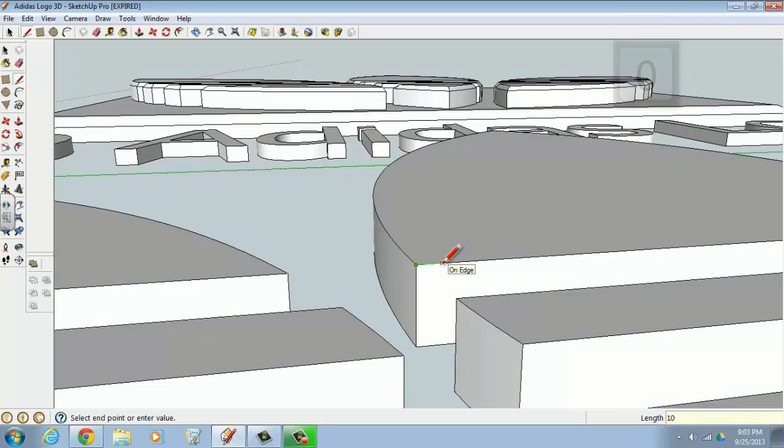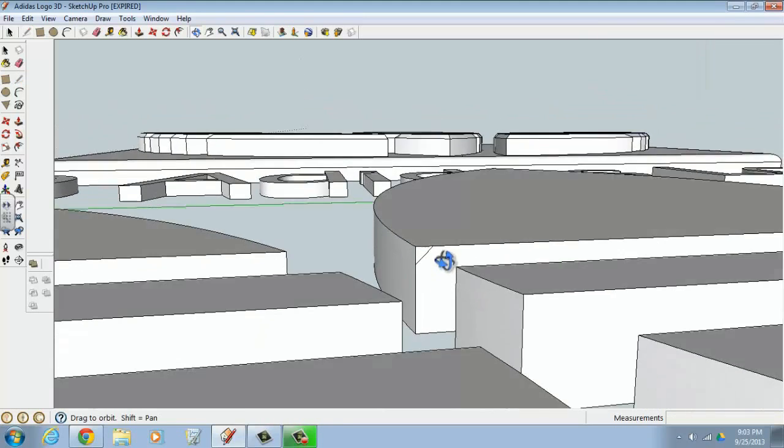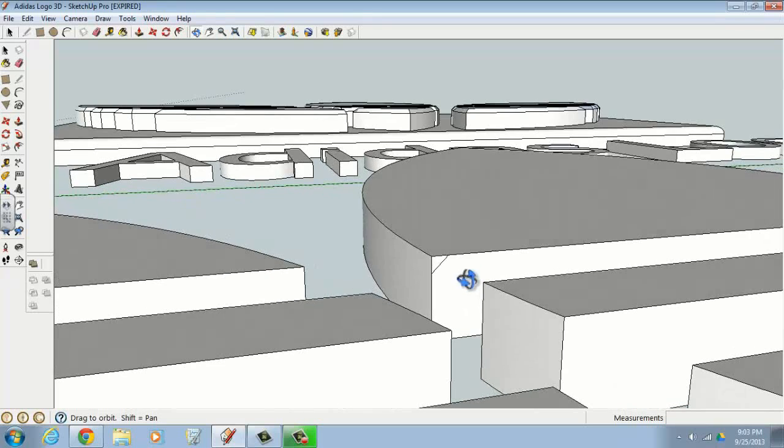You don't see it, but now doing that, we can snap to that 10 millimeter endpoint. Click on the corner again. We're going to make a 10 millimeter line down, type in 10, and now I can find that 10 millimeters and then snap to the other one, and it makes a little diagonal line. And this is basically what the bevel looks like, and then we're going to make it follow all the way around the surface.